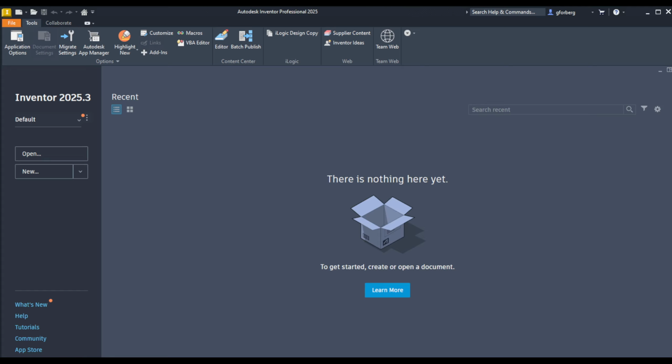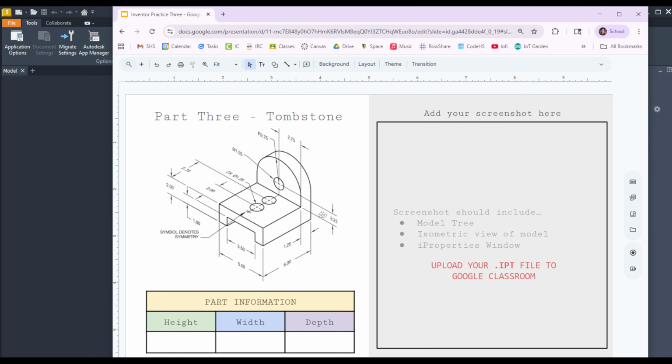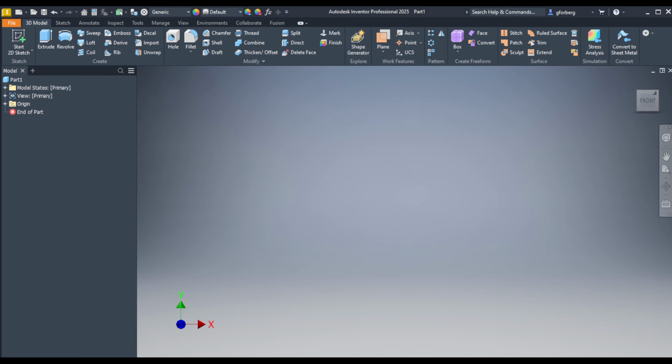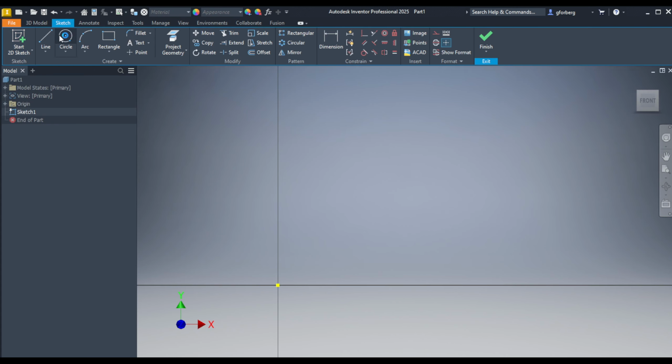To determine the shape that I'm going to draw, to start, I want the width right here, 5.5, and then I want to draw until I get to the center point of this circle. So to get up to that, I am going to use some dimensions and chain those together. We've got 2 right here and 3.25 here. So I'm going to draw a rectangle that is 5.5 by 5.25 to start. I'm using this combination of dimensions because we never dimension to the top arc of a circle. We always dimension to the center of a circle.